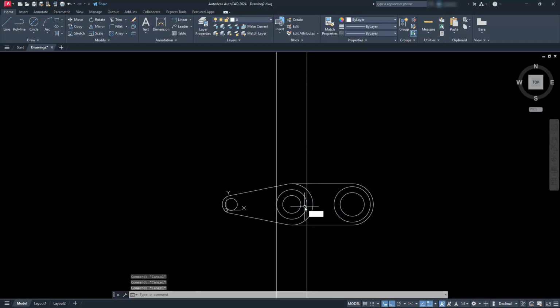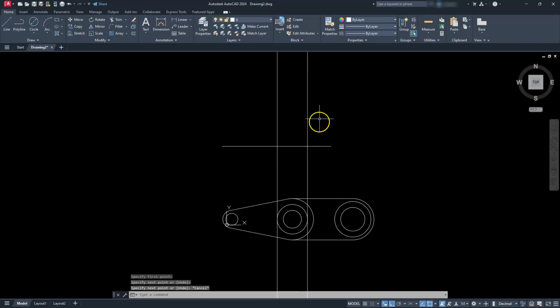All right. Start the line command, right? I'm going to shoot a line going right across here. And referring back to the drawing, the total distance that goes across here is 95. So I'll go to offset, type in a distance of 95, click this line here, and then click above it.